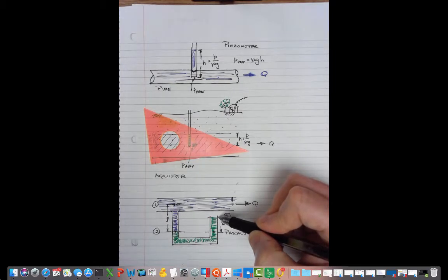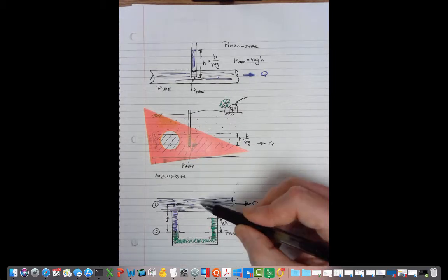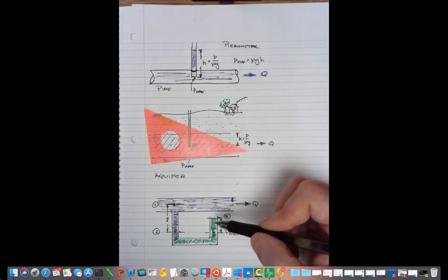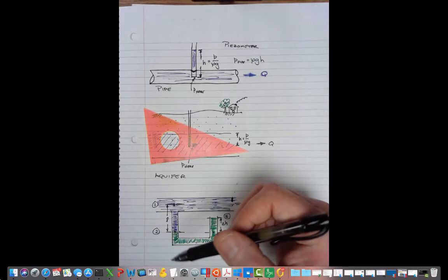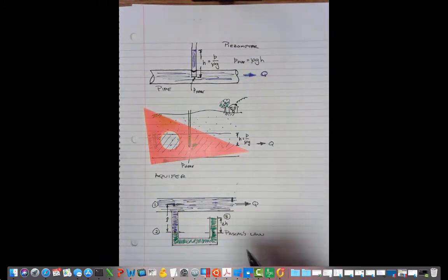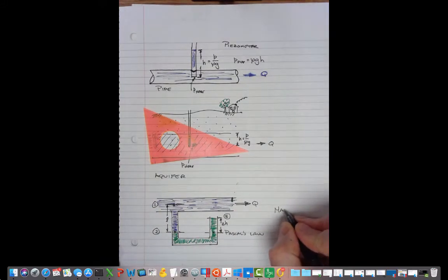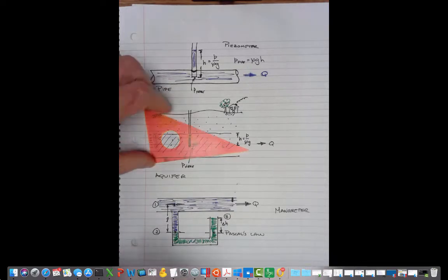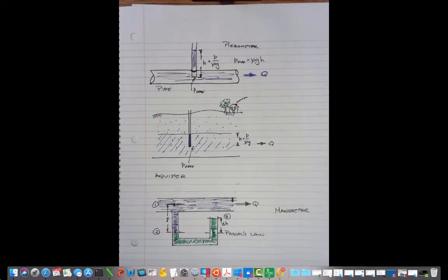And when we've done that, we'll be able to relate the densities of the two different fluids in this delta H to discover the unknown pressure at position 1. This device is called a manometer, and they are still in use today in both industrial and school applications, although most control situations aren't going to use manometry. They're more of a monitoring tool.